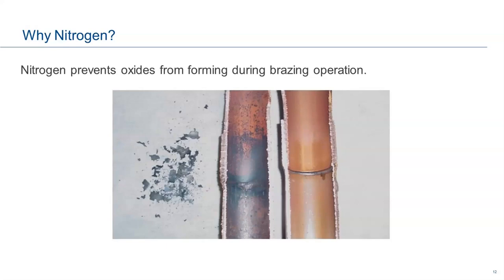And I remember the guys grumbling in the back of the room, the older guys, and they were all saying, oh, that's a bunch of bull and this and that. They told us that with R22, and it was nothing. But what they didn't realize, and these are the people I was learning from, and they're very smart guys, what they didn't realize, though, is we changed to POE oil. And POE oil changed the world.